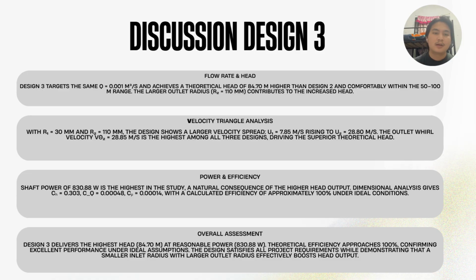So for overall assessment, design 3 delivers the highest head, which is 84.7 meter, at reasonable power, which is 830.88 watt. Efficiency approaches 100%, confirming excellent performance under ideal assumptions. The design satisfied all project requirements while demonstrating that the smaller inlet radius with larger outlet radius effectively boosts head output.